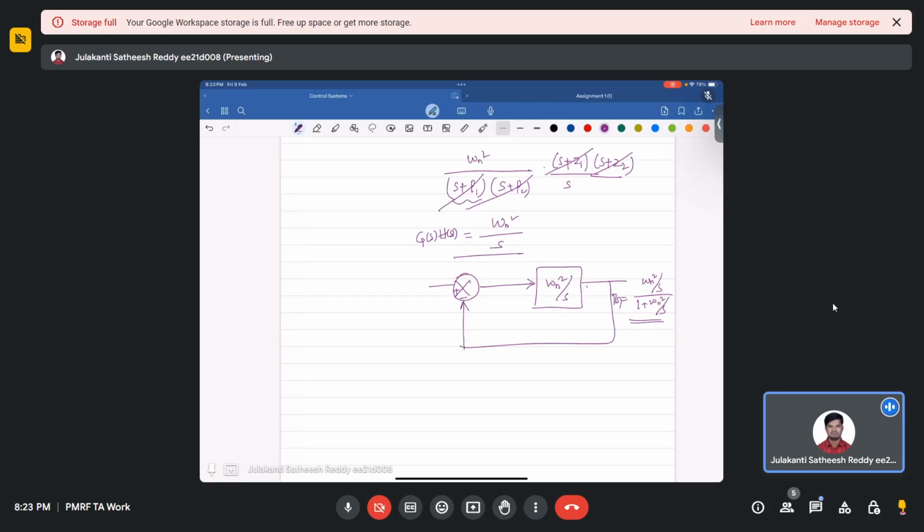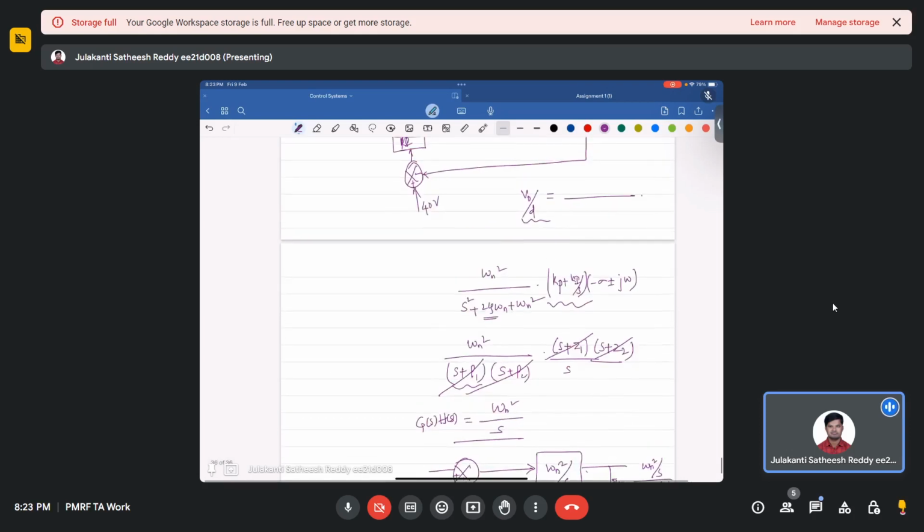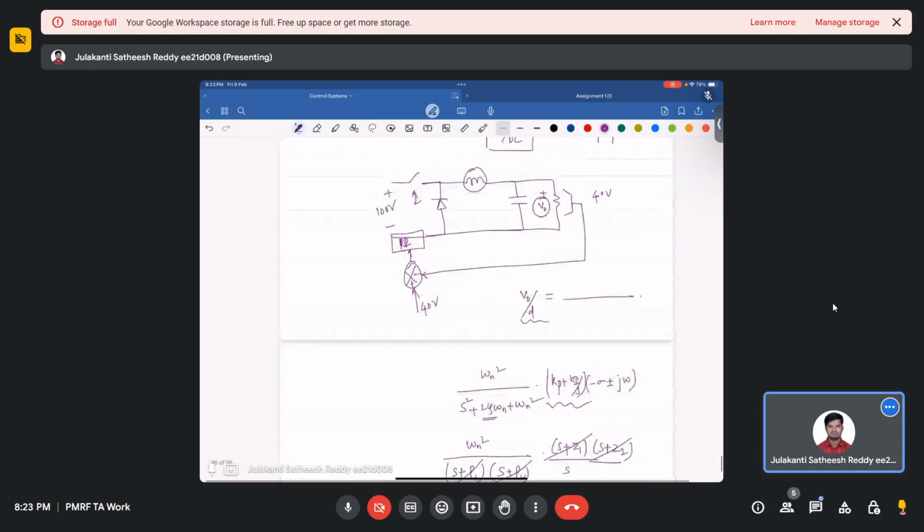So my point is that you are saying bandwidth. Now bandwidth is all about how frequently, what is the switching frequency of it, and based on that, how fast you need to bring the system response. Suppose you are designing this buck converter for a CPU processor, so you demand a very fast dynamic response. If you are designing this converter for maybe a mobile charger, you don't need to demand that much fast a response, so you can compromise there. So bandwidth is all about how much fast you want it.